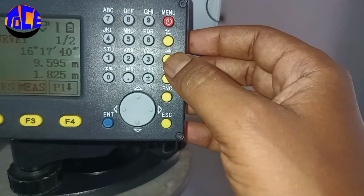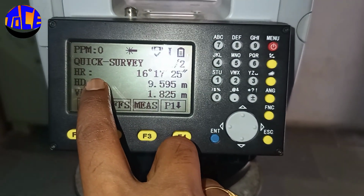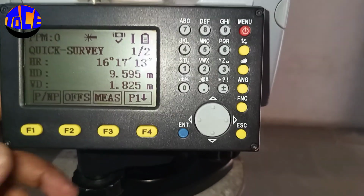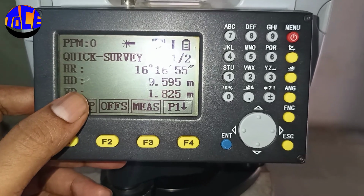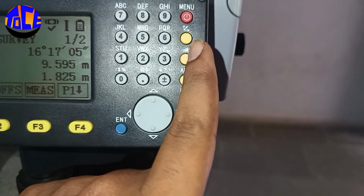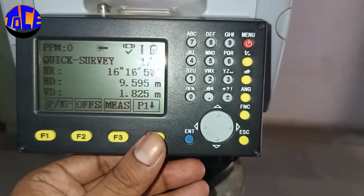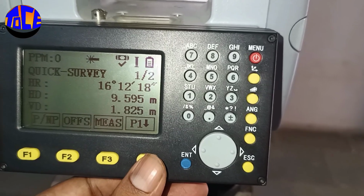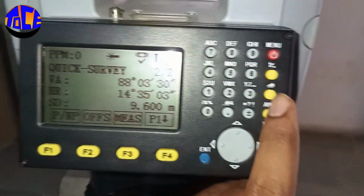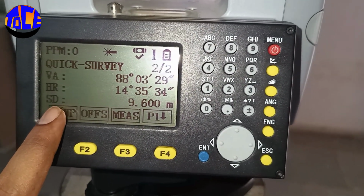Yes, so here you can see HR is for horizontal radius, and HD is for horizontal distance, and VD is for vertical distance. Okay, where is the slope distance? This symbol indicates that it can also measure the slope distance, but it is not showing here. So for getting the slope distance, just hit this button once again. Now you can see you have SD also. SD is for slope distance.